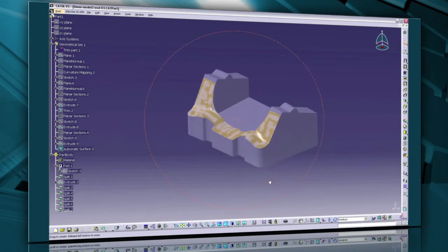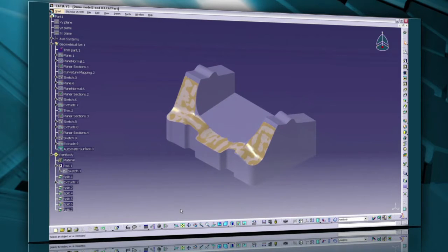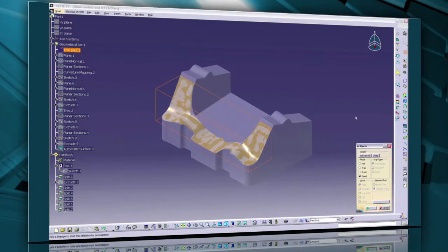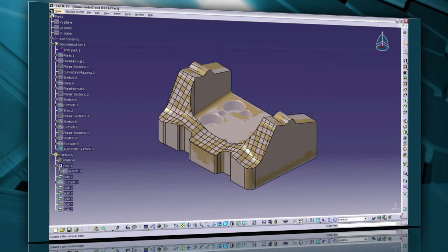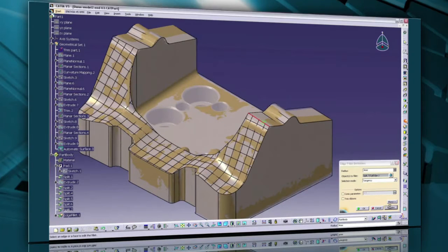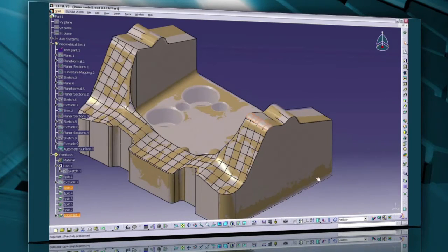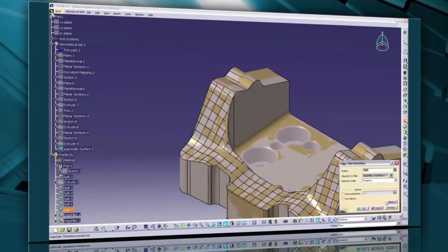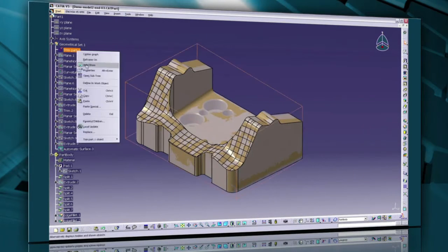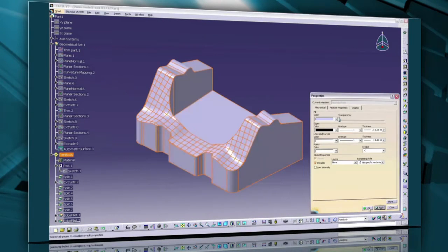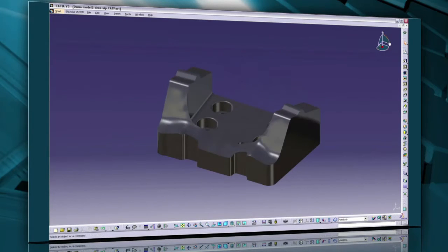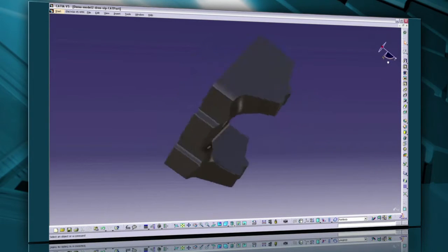After the main surfaces are created, you can use the usual tools of part design for the remaining operations. Easily create missing fillets and add features like holes and pockets. In this example, the whole procedure from import of the points to the final fillets on the body takes less than 30 minutes for a trained user, and is a very efficient part recreation methodology.